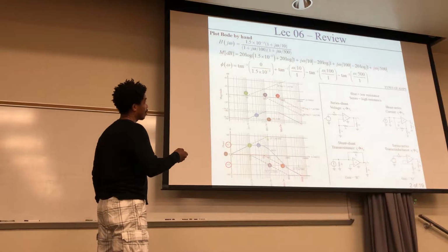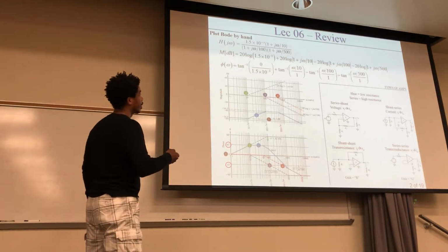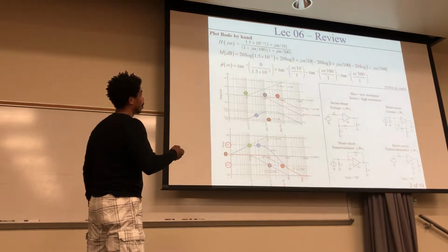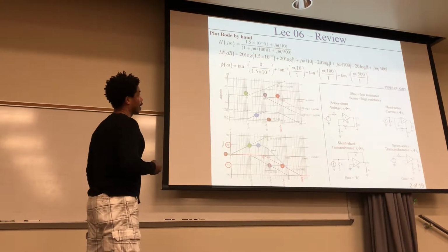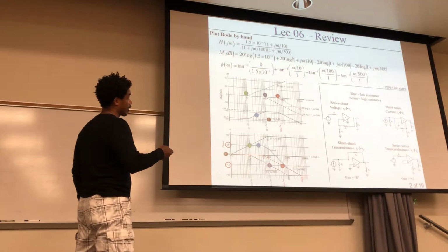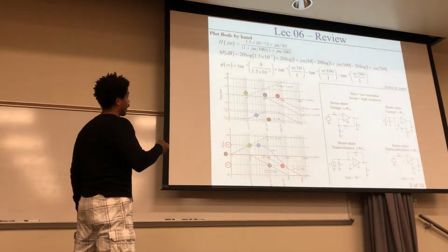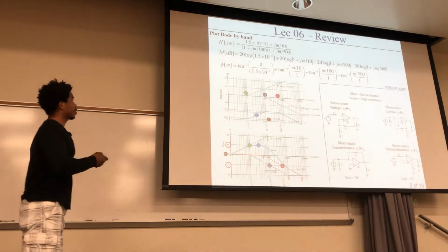And then when that omega equals 500, you have the square root of 2 as well. Okay, but 20 log square root of 2 is going to be 3 decibels, but it's going to be minus 3 decibels here. This becomes minus 3 decibels at that cutoff. At this cutoff, this becomes plus 3 decibels. Okay, and that's where you put the cutoffs at.